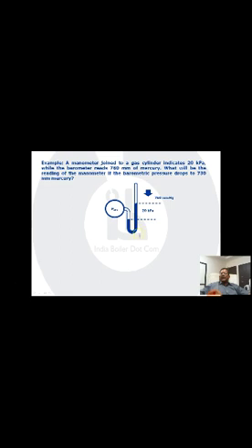It is filled with either mercury or water or whatever the measurement liquid is, and this pressure is more than the atmospheric pressure. Therefore, the liquid is going to push up. Now, if I take a look at this, the manometer pressure is the differential pressure between the atmospheric pressure and the actual pressure, right? What is important is that the barometric pressure may change, but